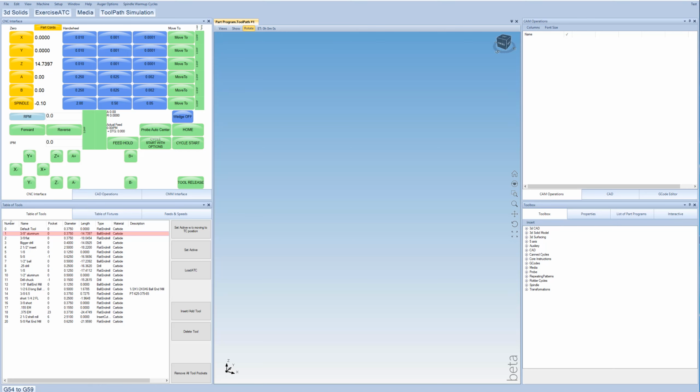This video is going to show how to use the GCode system in our C4 software. Essentially, in our toolbox, this is a list of all the instructions that the machine can perform. One of those is that it can just run a GCode file. So we're going to insert a GCode file into our main program list, click on it, and then we can switch over to the GCode editor where we can actually edit GCode.